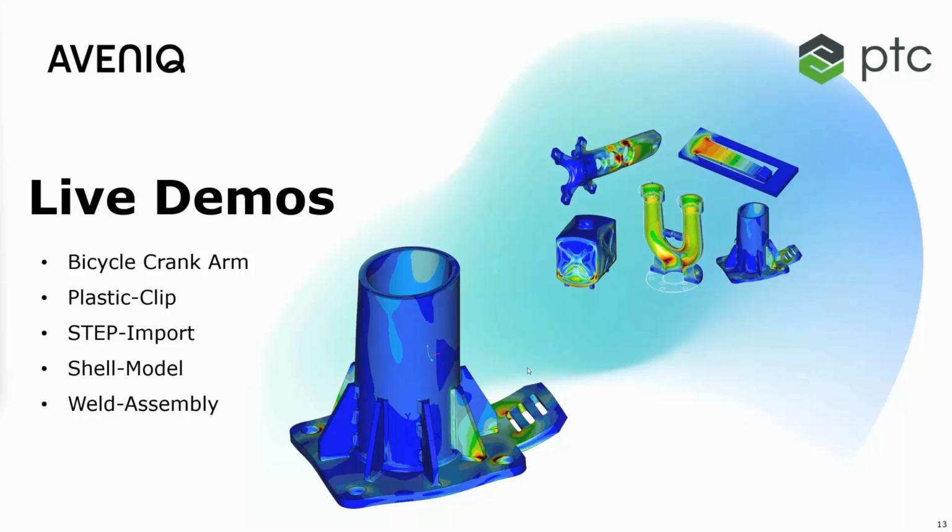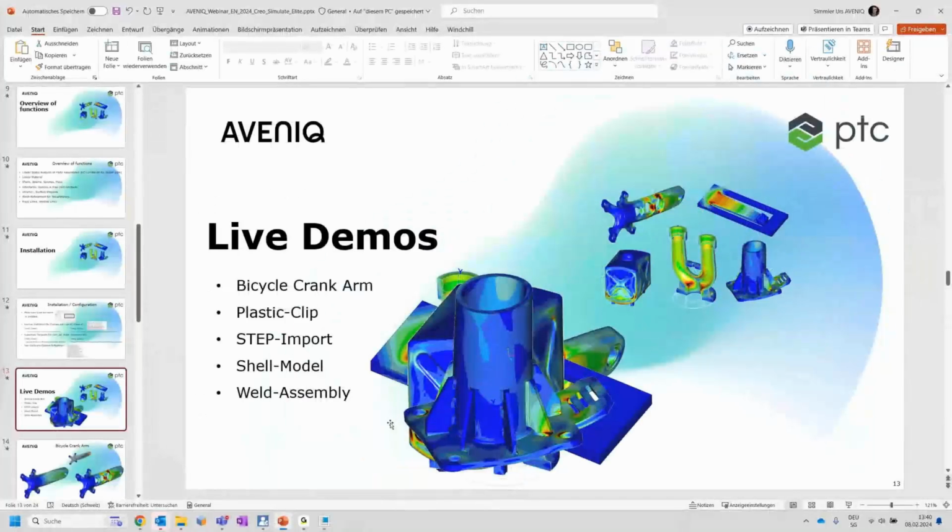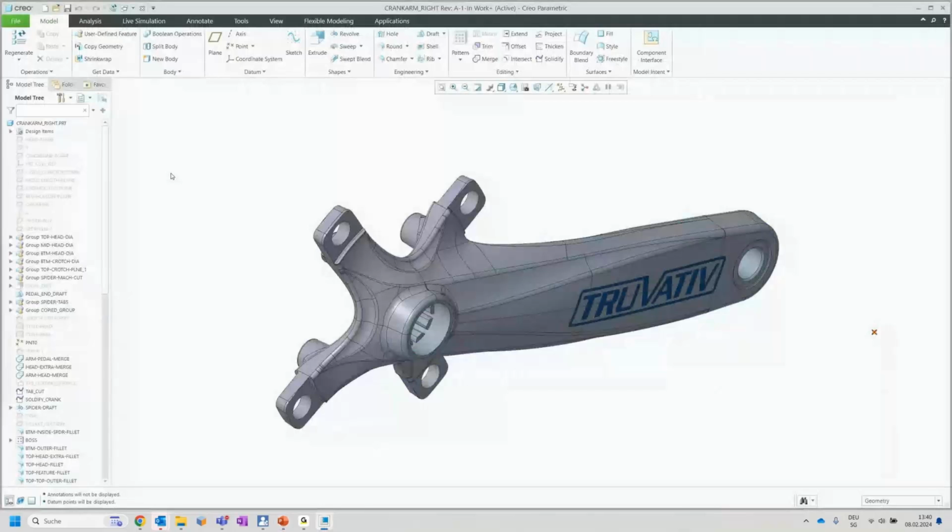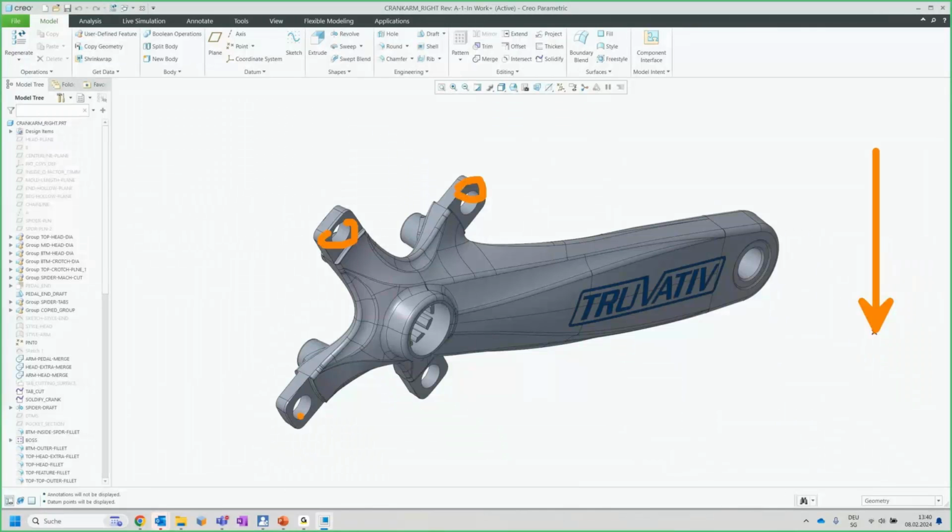So now let's go for Creo Parametric here. I started already Creo Parametric. I think it's a version 9. And you can also use Creo Simulation Elite in version Creo 4 or so. And the target of our analysis will be, here we have a load of 1 kilonewton. We constrain our component with these holes, and then we'll see the stress behavior.